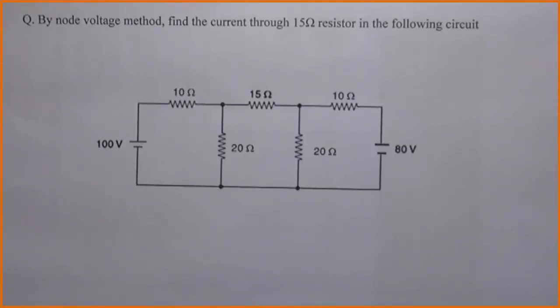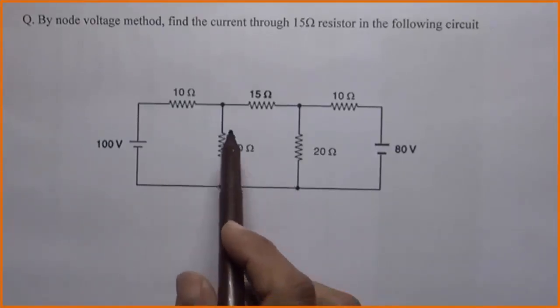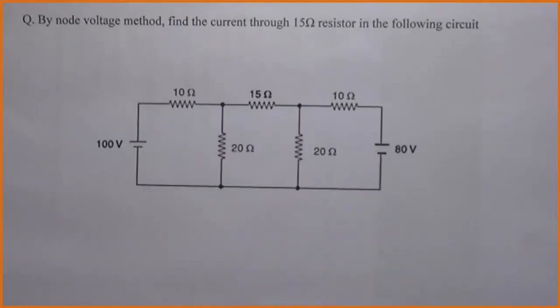a reference node. Generally, reference node is selected as a node where maximum elements of the circuit are connected together. To these nodes, maximum elements of the circuit are connected, hence it can be considered as reference node. Hence, our lower node in the network is considered as reference node. The circuit will be simplified by denoting nodes and reference node such as